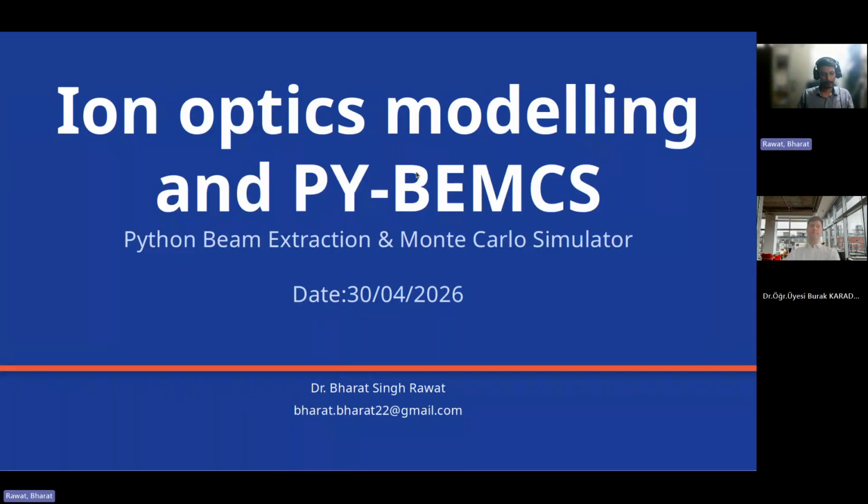Great. So today's presentation or lecture is going to be on ion optics modeling, in which I would cover some basic things related to designing ion optics and a simulation tool which I'm trying to develop called PY-BEMCS, which stands for Python Beam Extraction and Monte Carlo Simulator. And I will discuss the motivation for this project and how it came about during my PhD and so on and so forth.